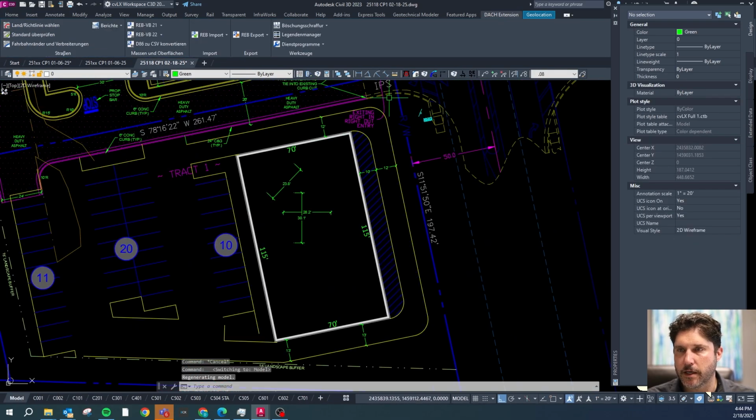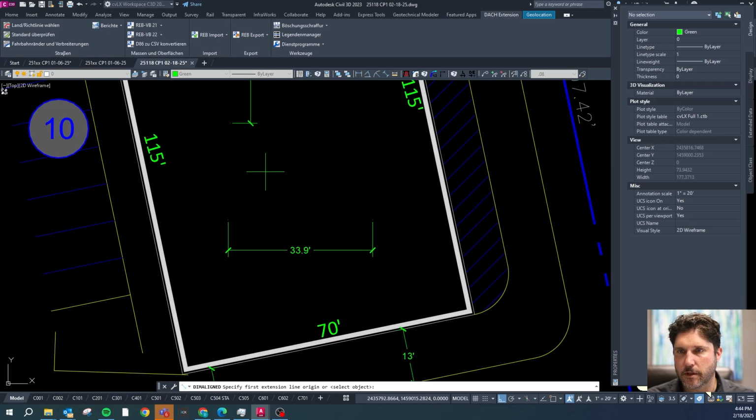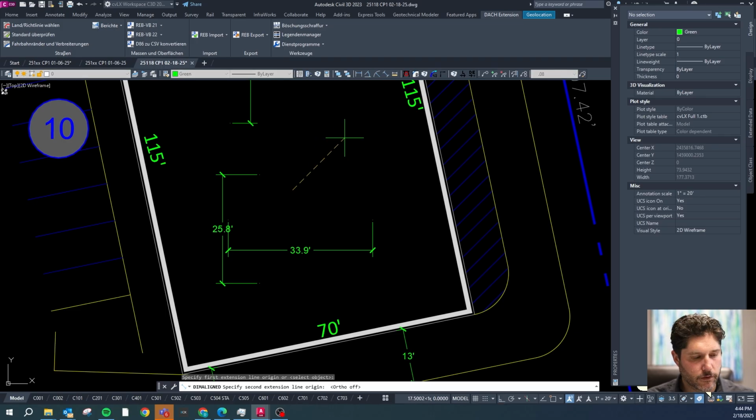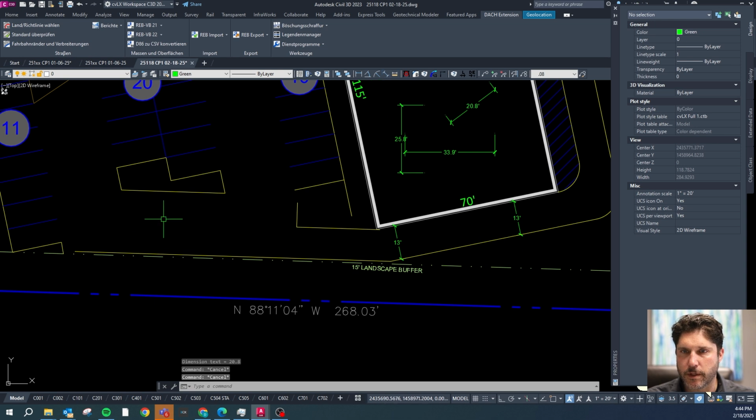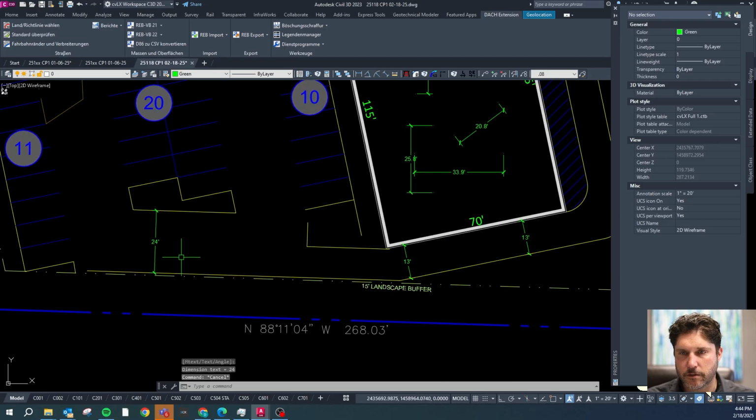And then I can come in here and I almost exclusively use this dimensioning tool right here, which shows the dimension at an angle. The reason I like that one is that I can keep my ortho on and draw dimensions horizontally or vertically, or I can turn my ortho off using shift middle button and do stuff at an angle. So if I was going to dimension this drive, I would click that button, do middle button space E or middle button space R for the nearest, and then middle button space P for perpendicular, and there's that dimension.